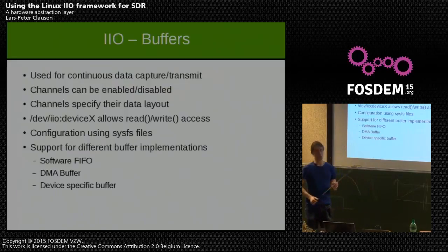And what the buffer allows you to do is gives you access to the data. It's represented as a character device. It's a normal character device exposed by the Linux kernel. You can read and write from it using the normal read and write functions.